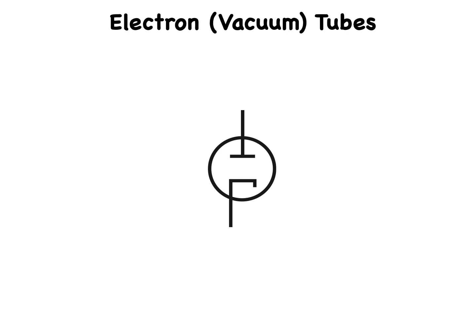This slide shows the schematic symbol for a diode vacuum tube. This 2-element device contains an anode, also called a plate, and a cathode. Just as with the semiconductor diode, the anode is normally positive with respect to the cathode when the device conducts current. The cathode emits electrons that travel through the vacuum to the anode, but blocks electrons from flowing to the cathode from the anode. This means that standard current flow will flow from the anode to the cathode, but blocks current flow from the cathode to the anode.